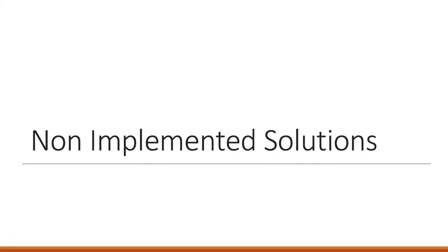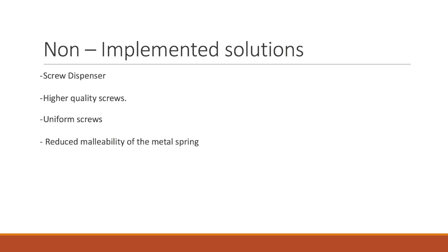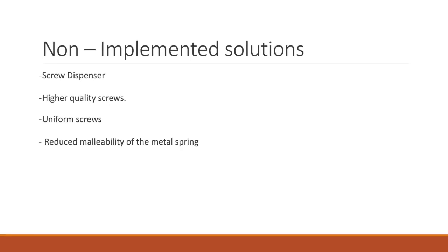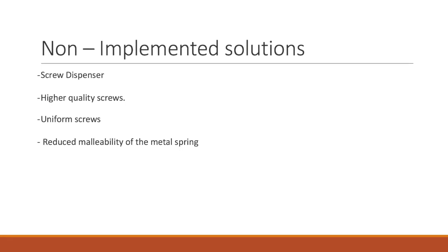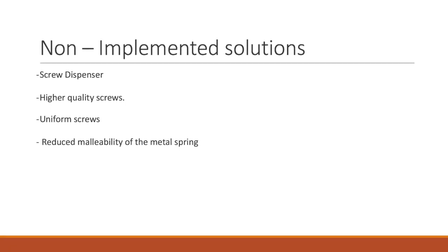Some of the solutions that we were not able to implement were a screw dispenser, higher quality screws, uniform screws, and reduced malleability of the metal spring. We wanted to incorporate a screw dispenser into each workstation to increase the speed at which the worker selects the screw to the corresponding location.